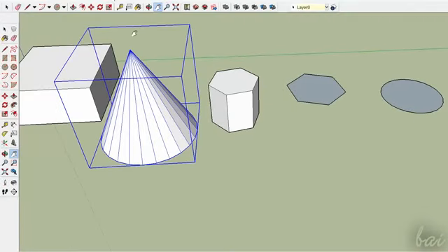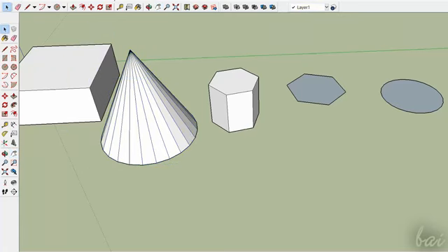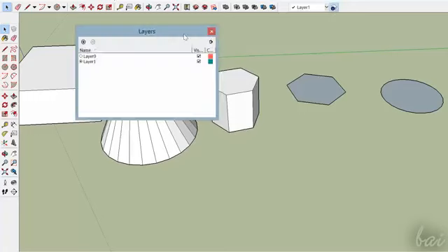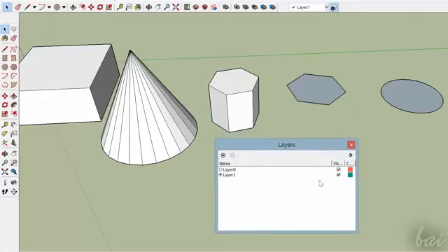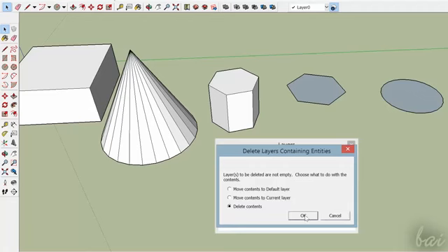It is important to associate layers to objects in order to hide them where you don't need them. In the Layers window, you can check and uncheck layers to make their objects visible or invisible. You can delete selected layers going on the minus in the top left corner.